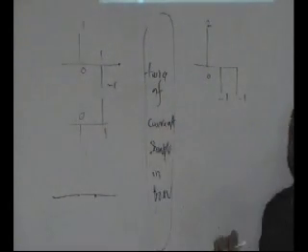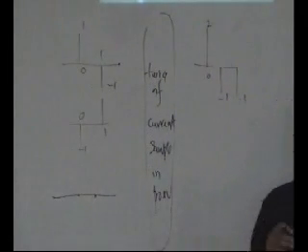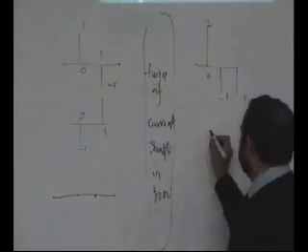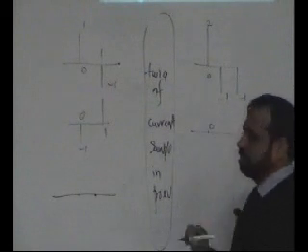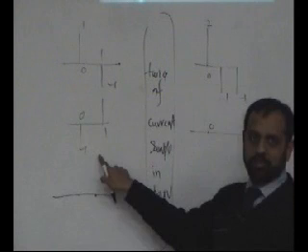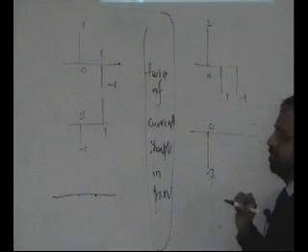Okay, so let's do the same here. Multiply the current sample. Current sample means for the index you are computing the output. If I am computing the output for index 0, 0 is my current sample. So multiply index 0 with minus 2, so you get minus 2, plus 0 is minus 2. Right?